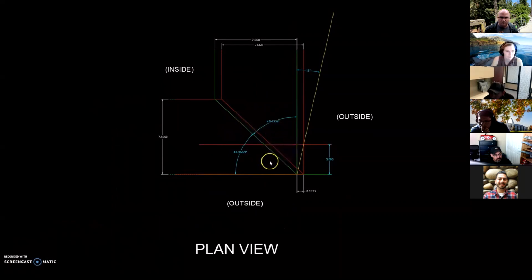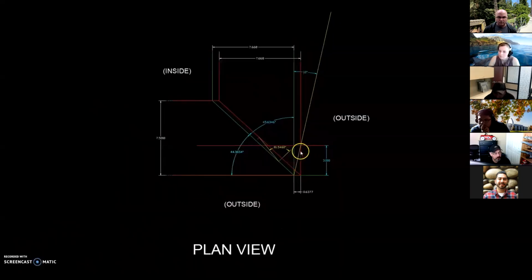As long as it goes perpendicular to these 2 lines, which are the miter lines contained on both the bottom and the top footprint. And project that down onto the layout to see and measure the tilt. Here we can see the section perpendicular to the miter lines already projected onto the layout.